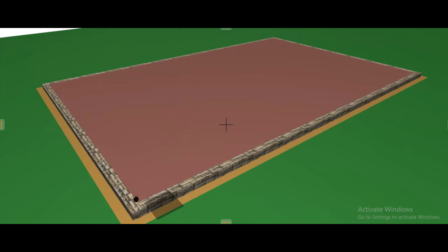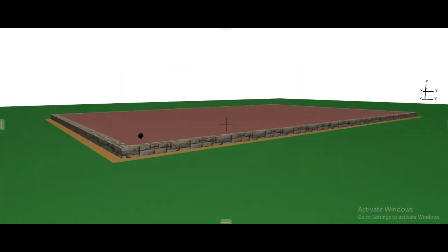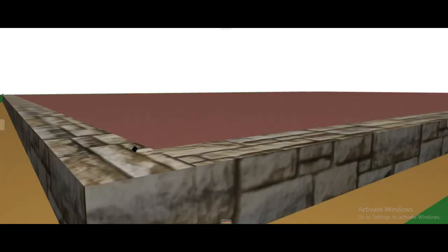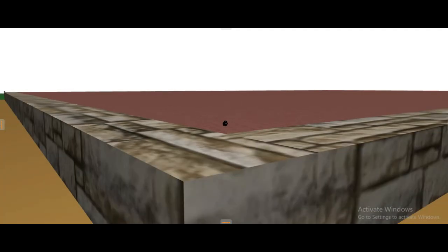but now it is 75 millimeters thick. Let me give you close range. It is 75 millimeters thick here. So if I'm interested to get the volume of that blinding, I multiply 0.075 by an area of 88.16, and the volume that I'm going to get is the volume of the blinding that I carry now to the Bills of Quantities.